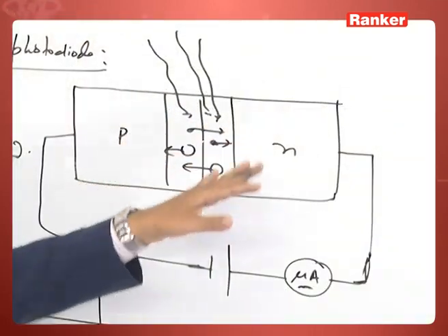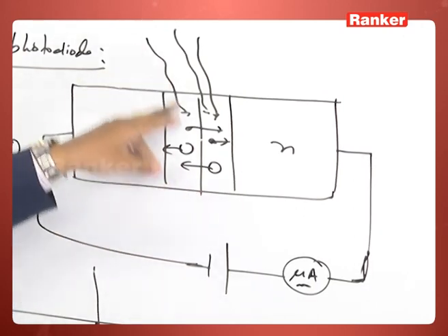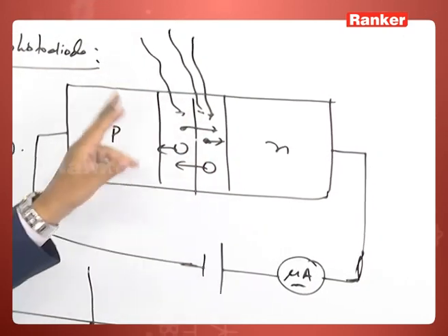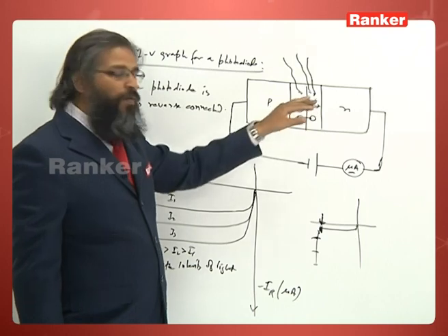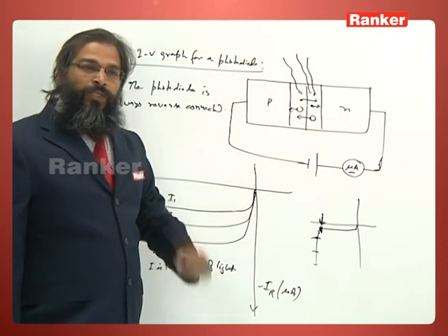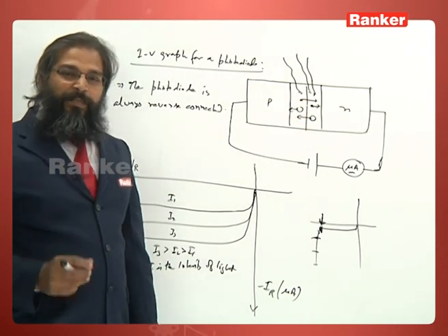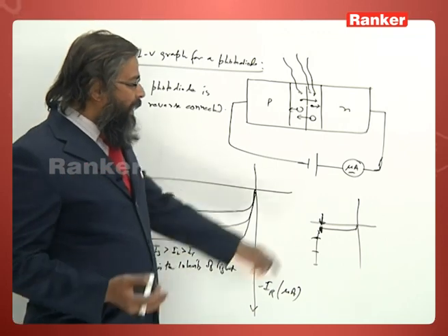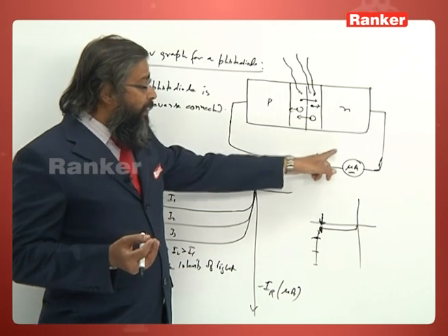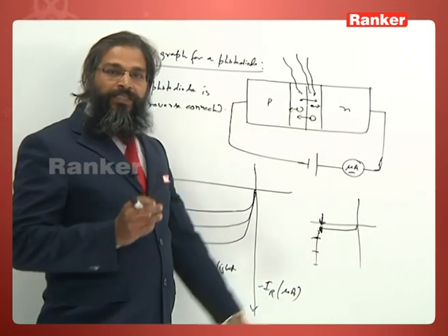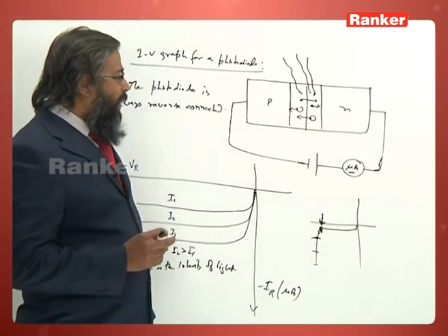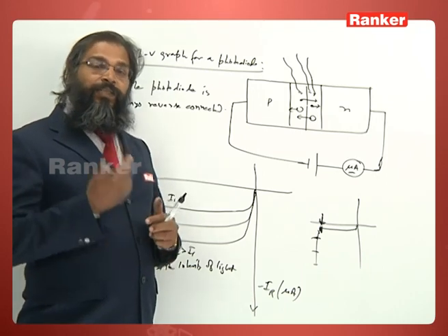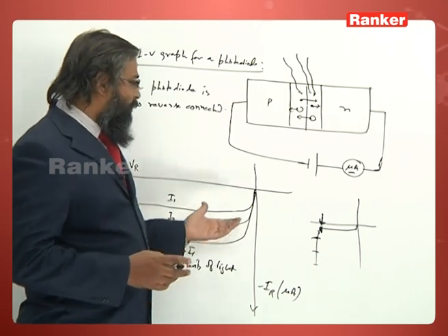But if it is forward bias, again the same thing will happen at the junction, but you see the order of current is in milliamperes. So, suppose a small increment takes place for a milliampere current, that won't be noticed, but a small change in microampere currents can be easily noticed. That is why the change is easily noticed in a reverse bias.